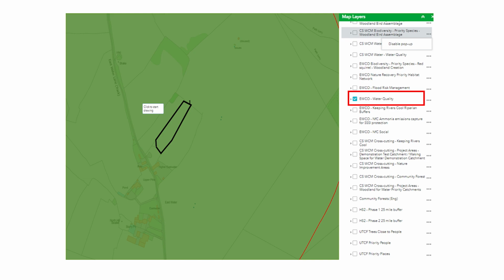Water quality. The purpose of this additional contribution is to improve water quality through woodland creation. It is important to get the species mix and the stocking density correct, as in some circumstances, woodland creation can have a negative impact on water resources. However, in the right locations, woodland creation can decrease or diffuse pollution through reduced fertilizer and pesticide usage. It can also protect sensitive soils from disturbance and erosion, increase infiltration and reduce water runoff, intercept sediment and chemical pollutants in runoff, reducing the delivery of pollutants to watercourses.